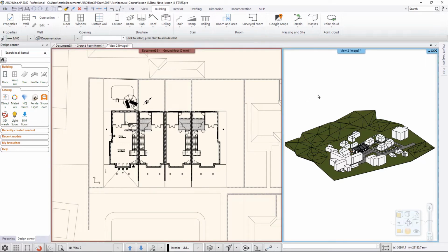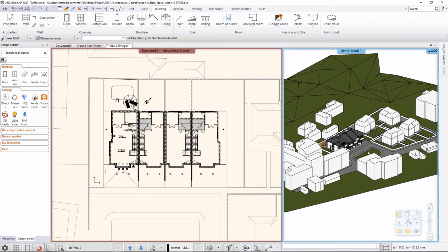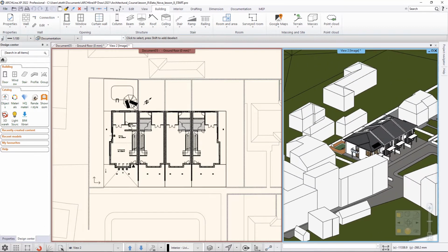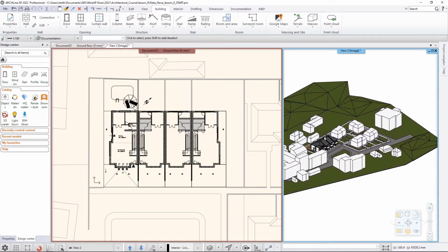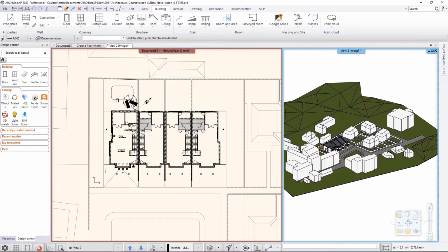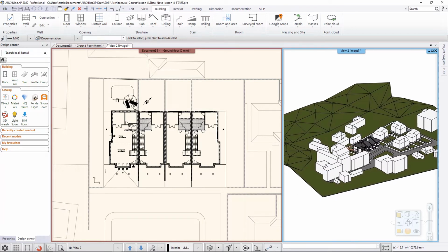First you need to activate the 3D and then you can hold your mouse wheel someplace of your drawing and scroll up to zoom into that area. Now move your mouse somewhere else, scroll up, and you will zoom into that area. If you scroll down, the software will zoom out in the same fashion as it did in case of the 2D. Panning the content is actually same in the 3D as it was in the 2D. You need to click and hold the mouse wheel, move the content, and release the mouse wheel. Do that again to move the drawing to another location.